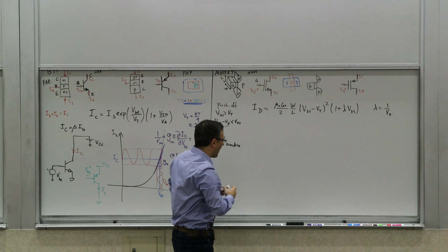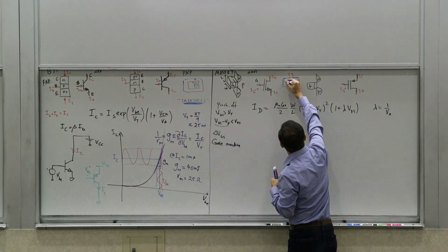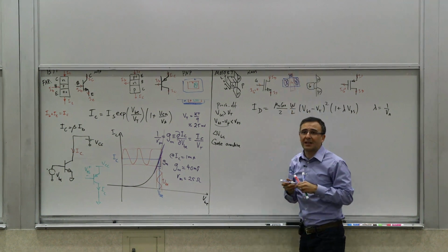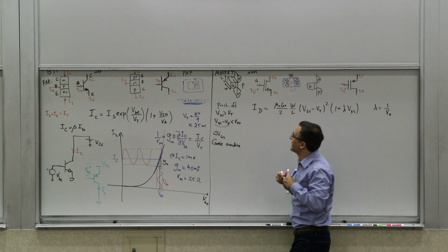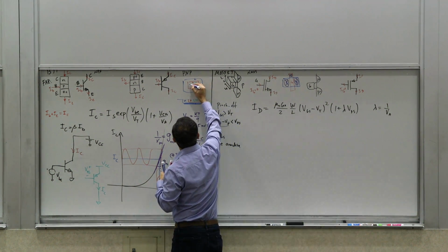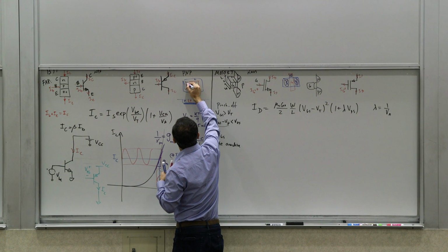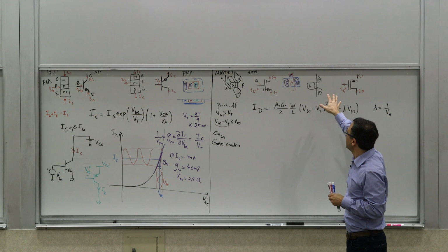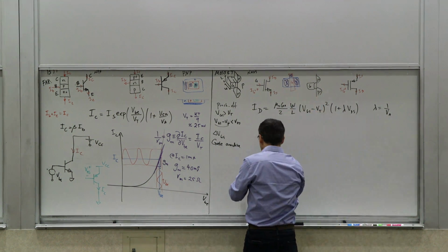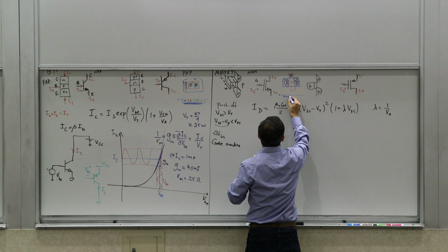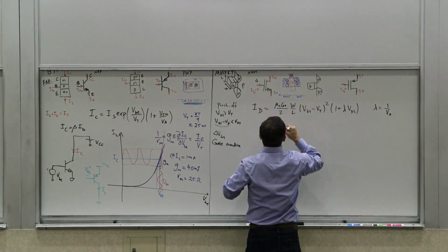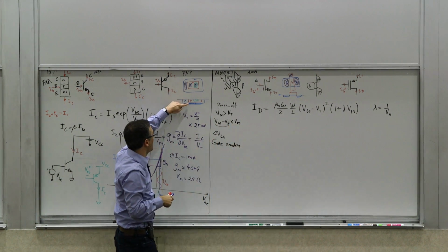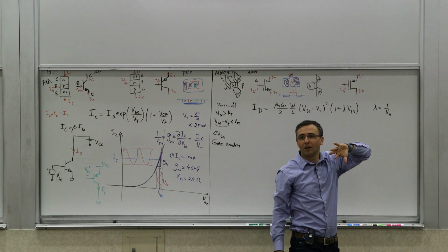Now, of course, these need to have contacts. So what you may see on top of that are these X's, which is where you make connections to these transistors. And the same thing here. You will have a contact here, a contact here, and probably a contact here to make connections to these three terminals. Now, are these pictures clear? If I do a cross-section of this, the side view looks like that. So top view, side view, top view, side view of the transistor, the way they are made.